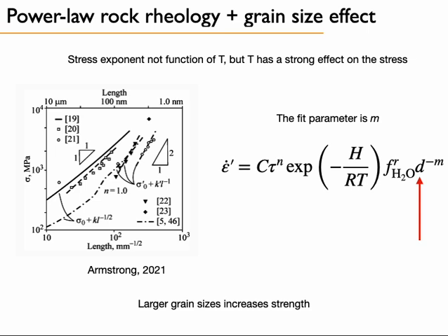Another important effect in rheology is the grain size. So here are again experimental data that correlate the stress to the size of grains. In order to take into account the effect of the grain size, we can further enrich our power law model by taking into account d, the grain size, so that's the new variable, to the power minus m, and m would be the fitting parameter we want to extract from the rheological data.